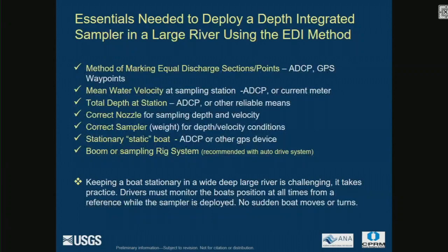I don't know if anybody still uses current meters. We have used them in the past. We still use them at times. Total depth at the station, of course, ADCP or other reliable sounder. I would recommend the ADCP. The correct nozzle size that you compute to use for your depth.